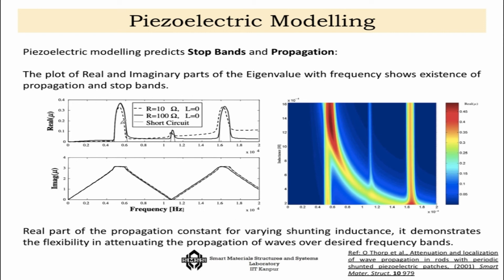So this is a pass band, okay, and this is a pass band. So there are two pass bands. There is a very small pass band here. Whereas wherever the imaginary constant comes into the picture, you may say that there are stop bands. So the creation of the pass band and the stop band is telling us that only certain frequencies are allowed through these channels and certain frequencies are not allowed through these channels.